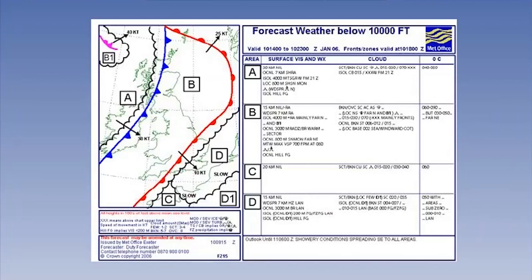Here is a table showing recommended distances from cumulonimbus activity. Pre-flight briefing is particularly crucial in weather where strong convection is expected. Low-level significant weather charts as well as TAFs should give a good indication for timings and location of cumulonimbus development. Use of onboard radar, as well as visual clues obtained by looking out of the cockpit, will also greatly add to flight safety in such conditions.